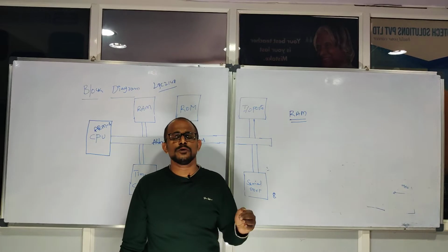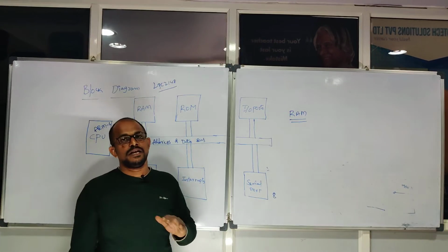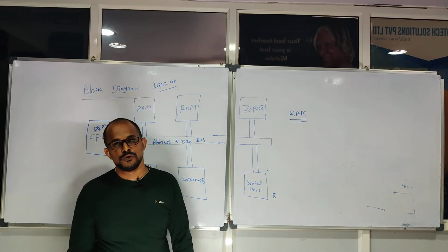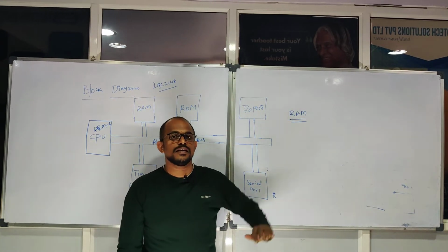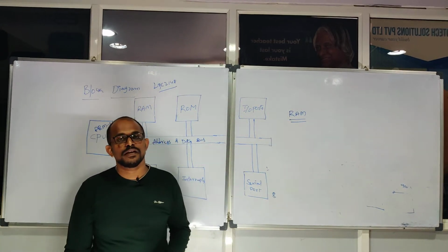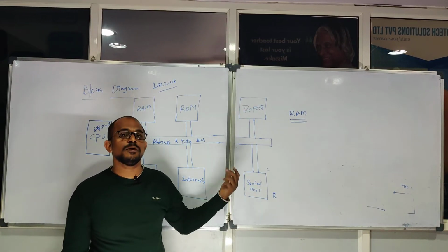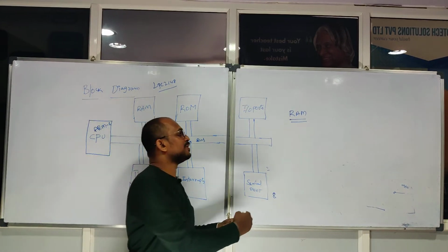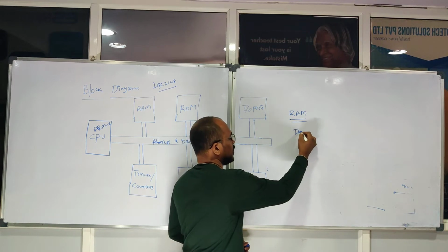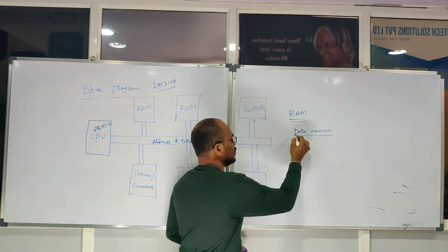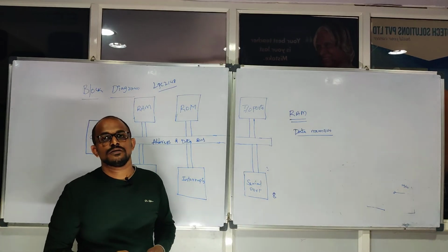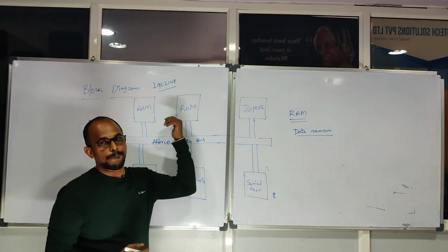Even though you are using registers in a program, indirectly it will use memory locations only. But which memory is it using? RAM. RAM is always helping us for temporary storage. And this memory is called data memory in microcontrollers. So any data you are trying to save in microcontrollers uses only RAM.